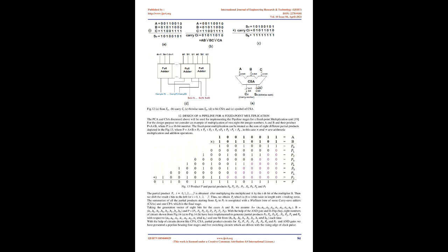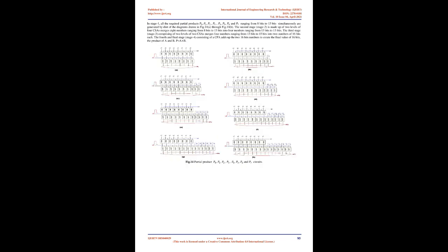On the basis of the pattern of the D flip-flop drawn in Fig. 8a, we can easily implement a D flip-flop with the help of threshold logic gate-based NAND and a buffer/inverter, shown in Fig 2a or 2c. The same parameters used in the case of a NAND and an inverter will be used in the TLG-based D flip-flop. The output is provided with the positive edge trigger of the clock. The input and output signals of the D flip-flop shown in Fig 9b through 9e are the D flip-flop input signal, clock signal, output of Q and output of Q-bar respectively.